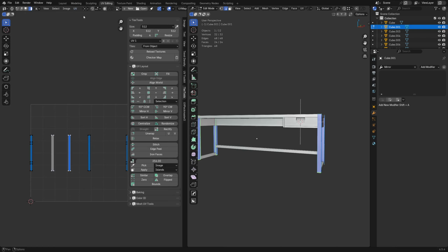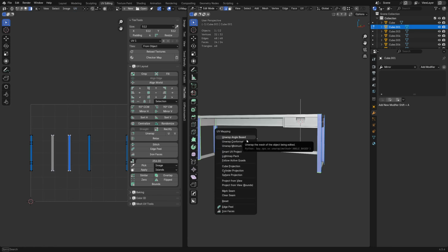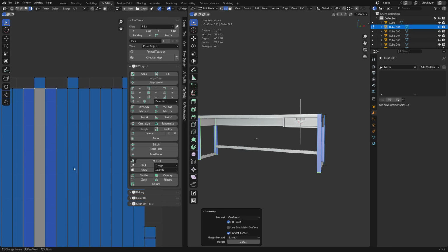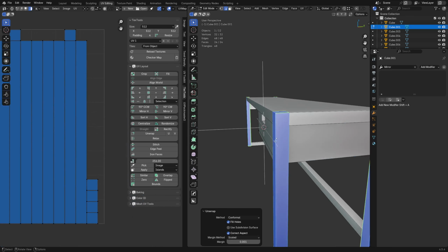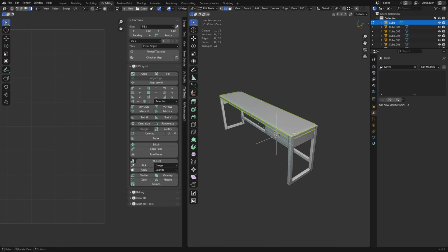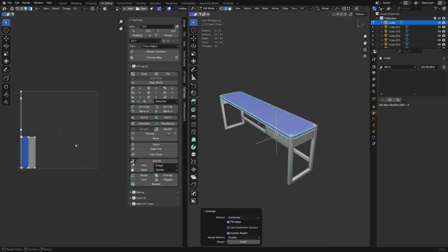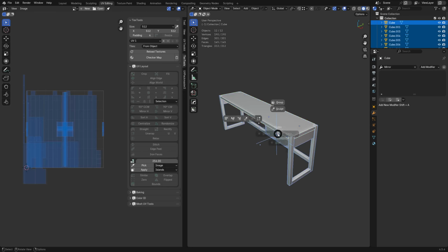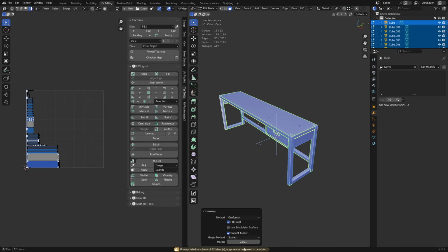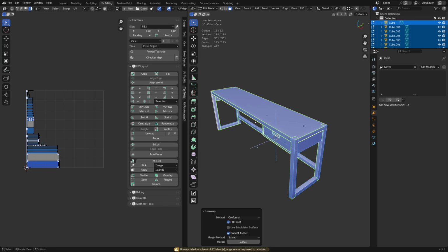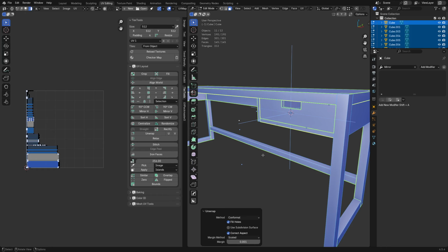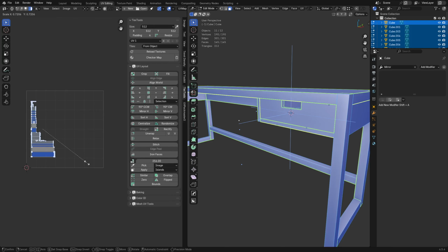And when those unwrap, press U, unwrap conformal, they stay attached like this and they stay seamless. So you're making little islands like this all over the place, is what you're doing. So when I unwrap this one, it does this number. Now, if I select all of this and unwrap all of it at the same time, this gives me an error. It means we missed something, right? So that's a possibility. The way I used to do this traditionally would be that I would scale everything to 0, right? So you can grab all of this with a S0, make it like so.